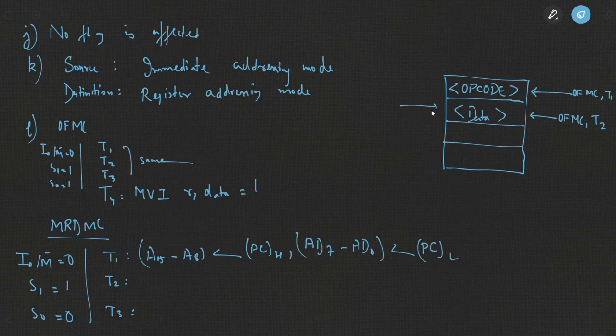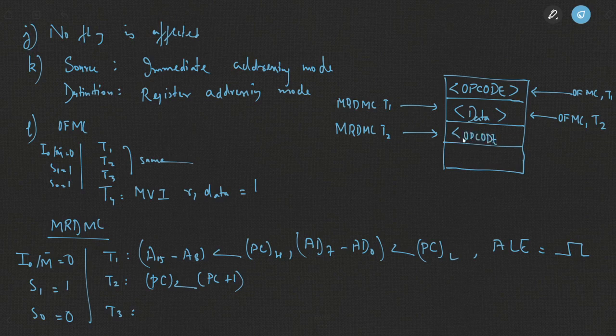So this now also becomes your memory read machine cycle. This is your T1 state. It's pointing to this location. Fine. We have loaded the address from the program counter, enabled the address latch, and in the T2 state now, as usual, since we have to increment the program counter, we increment the program counter. So now it will point to this location. This is memory read machine cycle T2 state. So the next instruction will be written here. Say for example, there will be the opcode of a next instruction. Once we do the programming, we'll see how this is actually happening. Program counter is incremented.